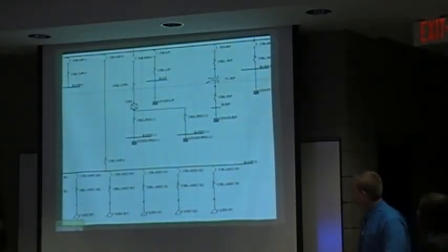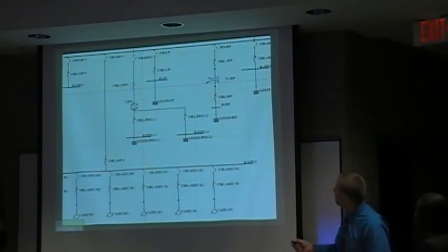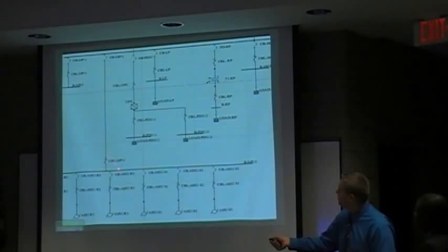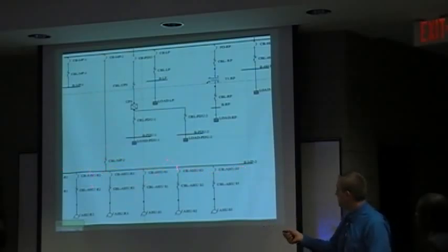Just a blow-up view of the mechanical panel 2. We have our running circuit breaker here, and then our cable here, and then this is our mechanical panel 2 panel, which is serving some of these air handling units here. I'm going to talk a little bit about this air handling unit S1.